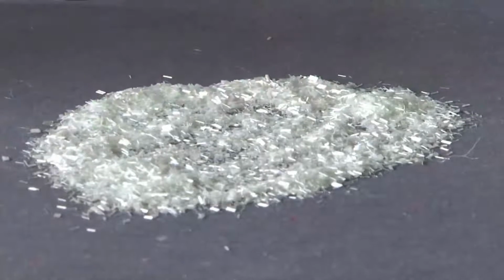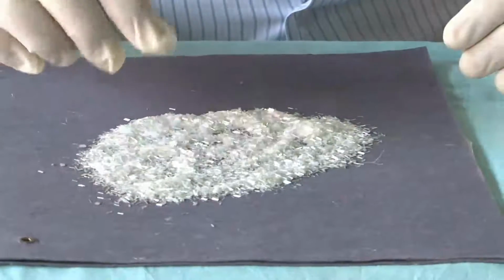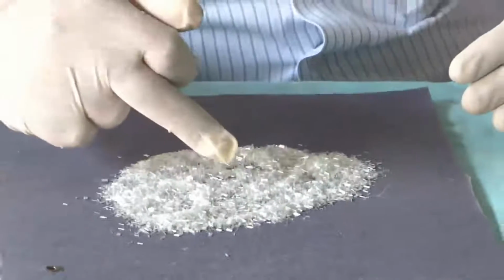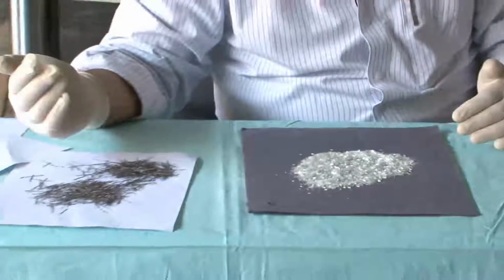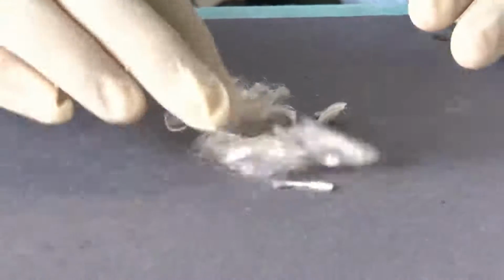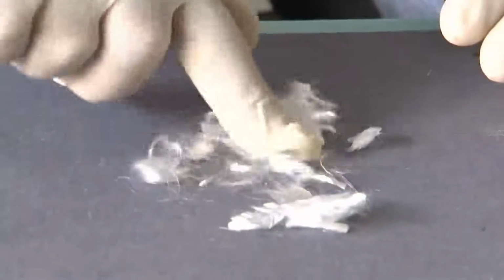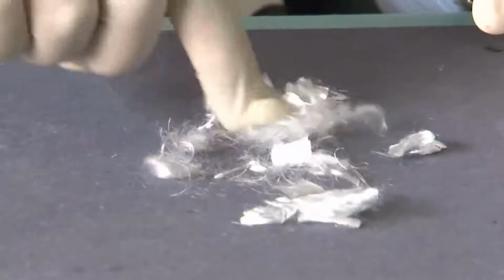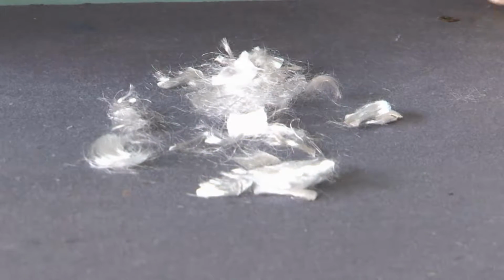These are glass fibers. You will notice that they are much shorter, at least the sample that I am showing you is much shorter than the steel sample that we saw just now. Other than glass, we also use polypropylene fibers, which is being shown here. Now, these fibers are again very difficult to work with as far as the ability to mix in concrete is concerned.